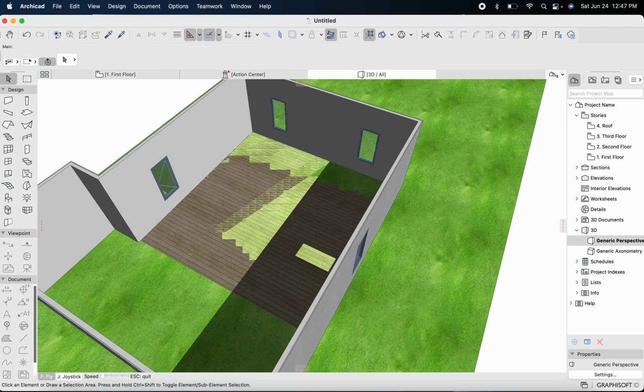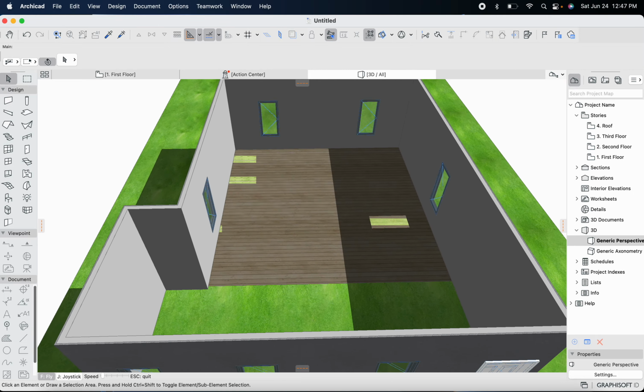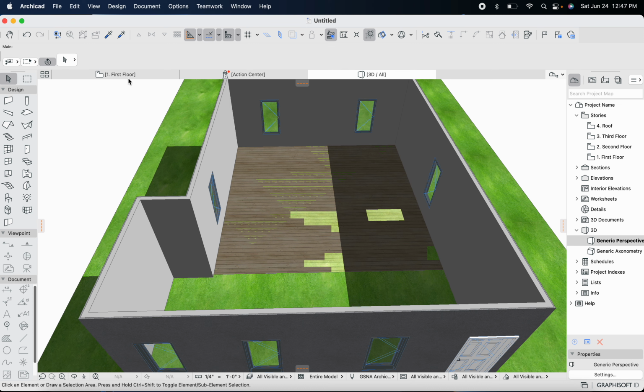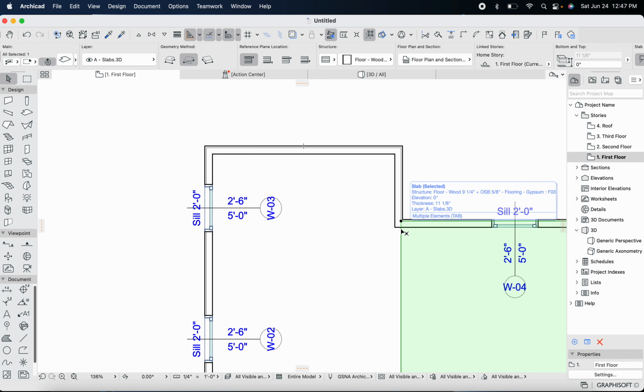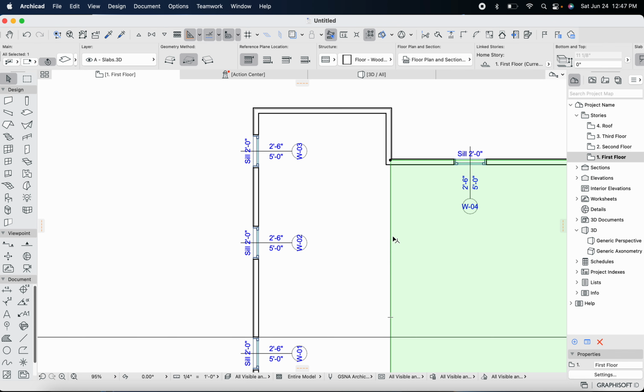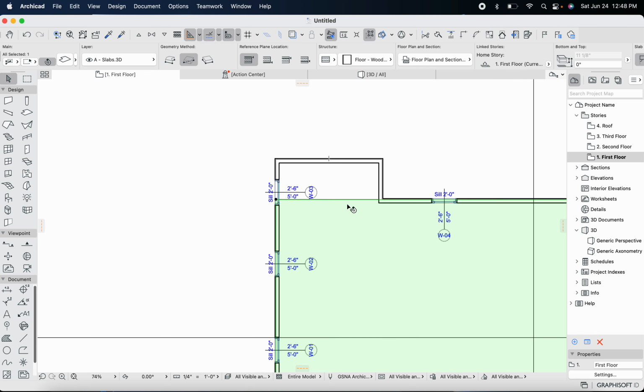You can see that it's intersecting with the terrain there, so that's why it's kind of glitching. So we'll fix that in a minute. But let me go ahead and head back into 2D view and show you guys a neat trick. In order to extend this floor, there's a couple things we can do, right? Here's the first option, which sometimes is preferable: if you just extend out, use this offset edge tool, it'll extend it out to where you want it to go.